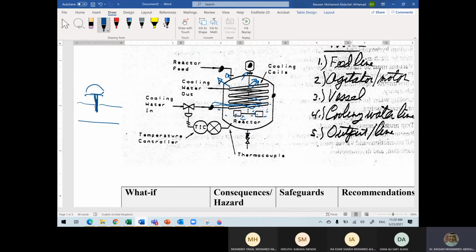Now I'm talking about a gate valve. This is why I just put one straight line here, and if it goes down, it blocks, and then like a gate, it goes up. Here, because of the air pressure that pushes the spring, this goes down and closes this pipe.